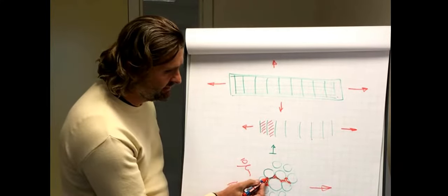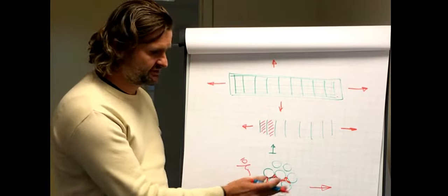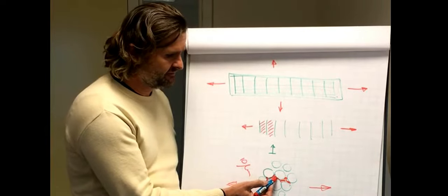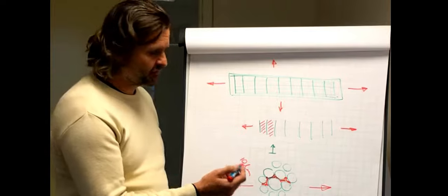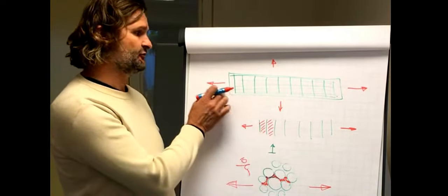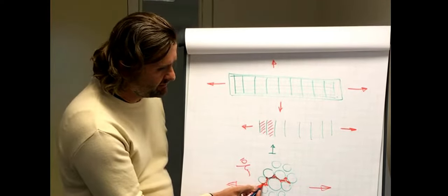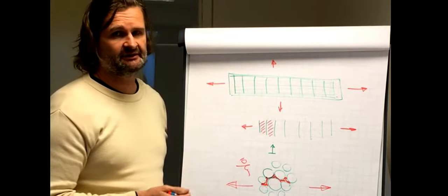But there's only very little resin to do that. So the flexibility of this layer is a combination of the flexibility of the glass and the flexibility of the resin. So even if I were to make the epoxy resin a lot more flexible to allow more deformation and therefore to allow more load, I'm only using maybe 20% in the total bulk of the material of that flexibility.